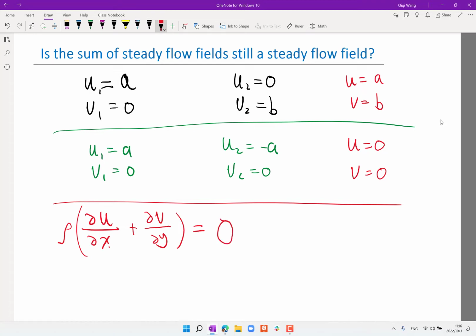That's how the conservation of mass equation is derived. Our TA derived it in the first recitation. For steady state, you cannot have the mass inside the volume keep decreasing, because mass is going to eventually become negative. That's impossible. So this has to be equal to 0.